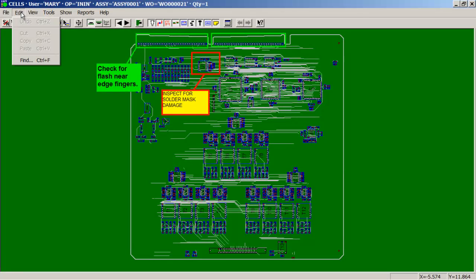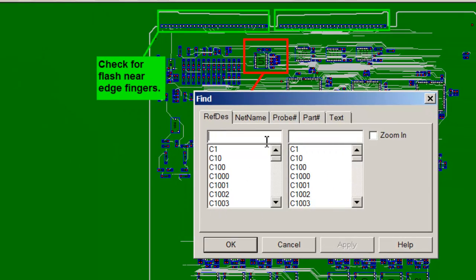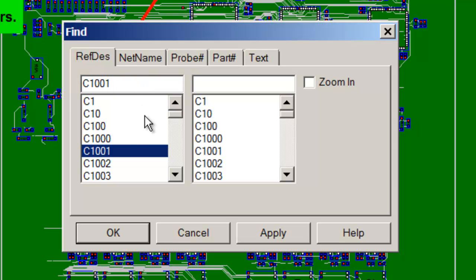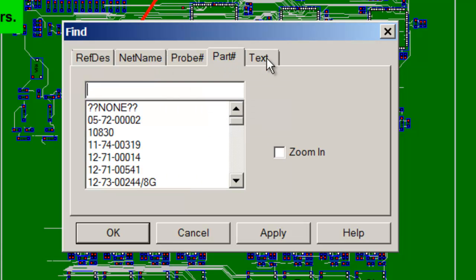You can search for elements. For example, if you're dealing with electronic manufacturing, you can find reference designators, pins. You can also find traces, highlight particular traces. For example, you can highlight 2 traces to find a short underneath a device where the 2 traces may meet, that type of thing. You can search by net name, bill of material information, etc.